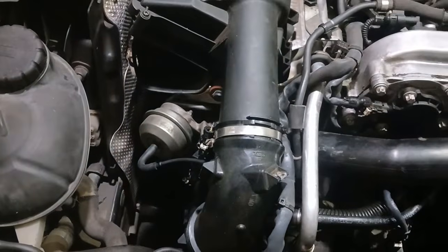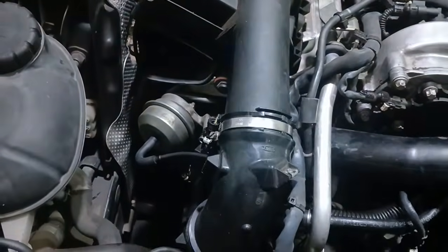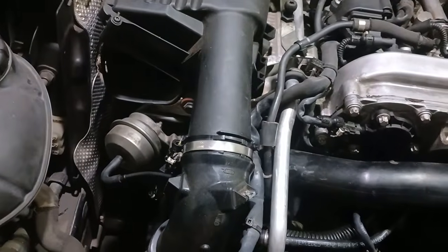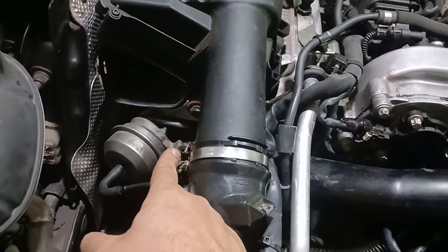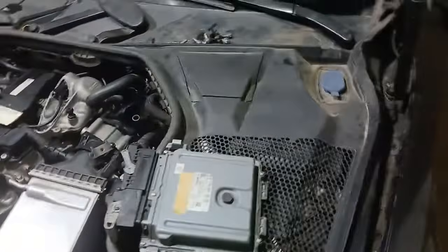So now we have here a fault code. If we connect the connector, we will have a short circuit. If we disconnect it, we have an open circuit. Also here we have two wires. We check it. We are having power here, and the signal or the pulse width is connected here and nothing on the wiring.